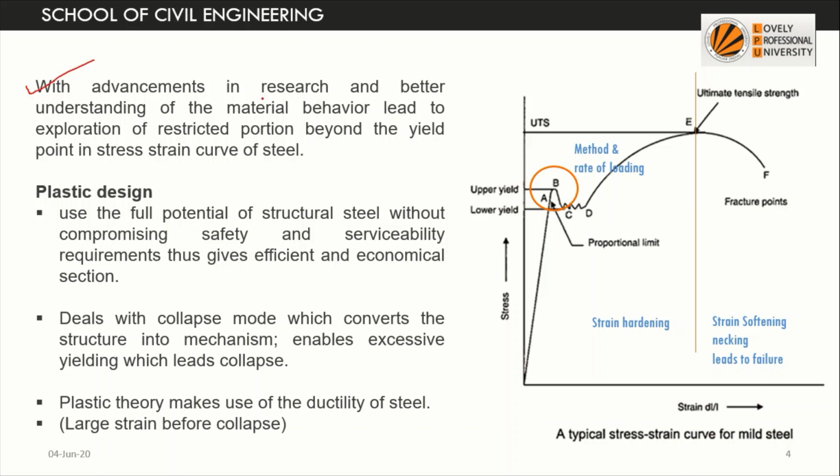With the advancement in research and a better understanding of the material behavior, we were led to explore the restricted portion beyond the elastic limit. When we felt confident about the material, we tried to explore this region, the region beyond the yield point in the stress strain curve. In plastic design, we use the full potential of structural steel without compromising the safety and serviceability requirements. So in plastic design, whatever sections we give are very efficient as well as economical, because we are considering the higher strength of the material.